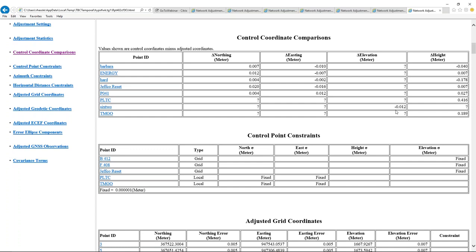Now in the United States, you can get national agency points mixed together with county points, mixed together with a city's control points, all of which have their own adjustments to them, and they may not fit perfectly well together. So if I'm trying to fit a national benchmark with a county benchmark with a city benchmark, that's all I have for control. I may find that they don't fit together very well.